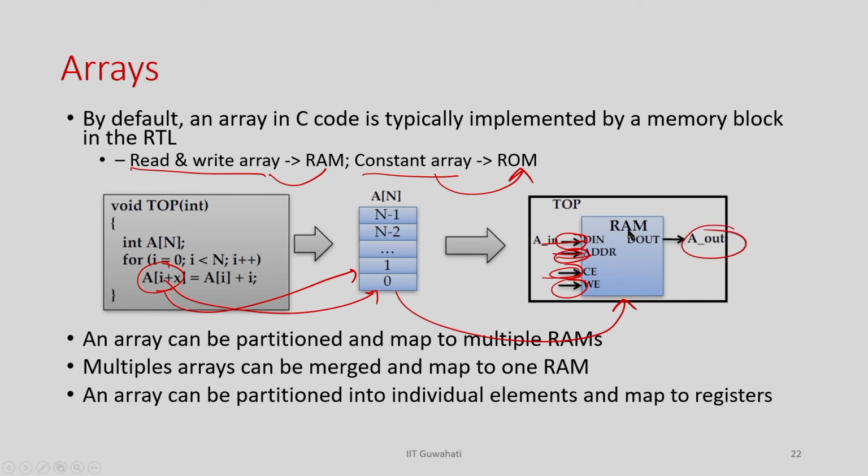Okay. So, this is how the access is going to happen, but in the hardware this RAM is not exactly like arrays, where you can access any content at any time. Rather, in the hardware this RAM will be accessed using ports, either a single port or dual port. So, that creates a lot of bottlenecks, and I will put a significant portion of this course time to talk about that.